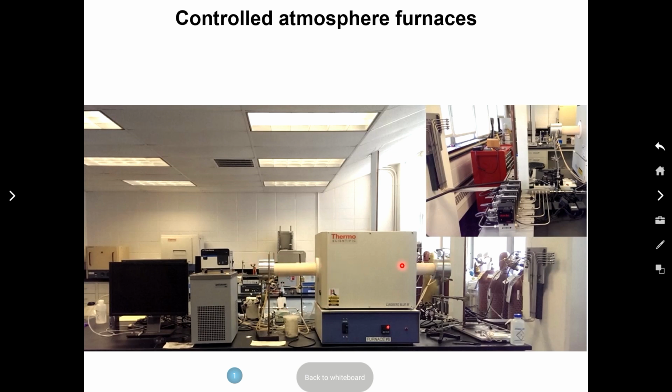For high temperature work, you use a ceramic tube like alumina. Alumina is better, more stable, and you would probably be going to 1500 degrees Celsius. And these ends will be red hot. So for safety reasons, they put stainless steel end caps on the gas tank, with O-rings.